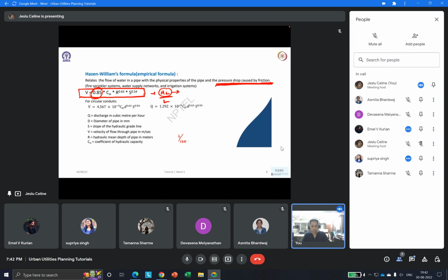As Supriya said, this is exactly where we have that in our main equation. But if the friction slope varies a lot and we don't vary this numerical constant, we can get plus or minus 30% to up to 50% error in our design. So this also we discussed.